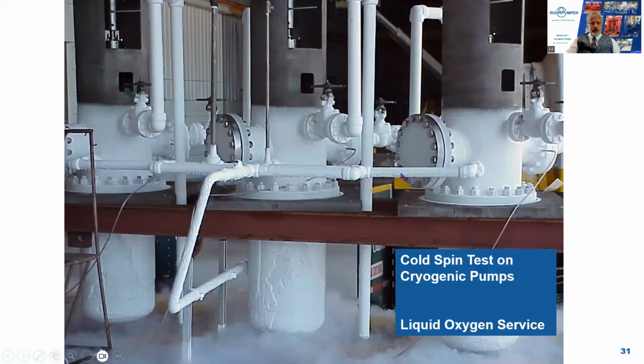Just a couple of photographs now. Here we have some pumps undergoing a cold spin test on liquid oxygen. So the flow is coming in through the drain connection, down and up through the pump and out of the vent connection. Again, you can see how ice formation stops directly above the pump nozzles.